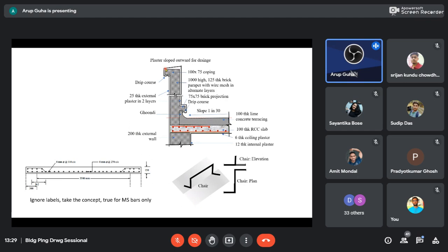Then up to a height we have put the plasters. So the plaster is in a lower elevation and this is in a higher elevation, so rain water, if it comes like this, cannot access this interface. But if water comes here, it can trickle through this interface. This interface we are protecting through the groove.